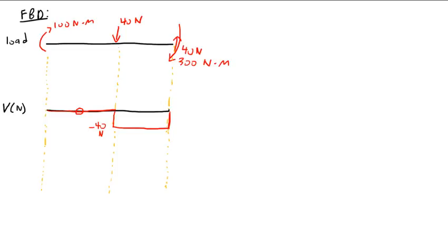They're finite, but they're vertical. So the two applied moments will not affect the shear. Well, the one applied moment. Oh, sorry, the one. Yeah, the one applied moment will not affect the shear, but it will affect the reaction moment here. Now, if I did have, say, a pin support or roller support here, that would affect things a great deal, because then these could generate a couple to resist or something like that.